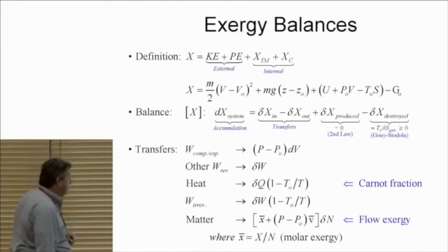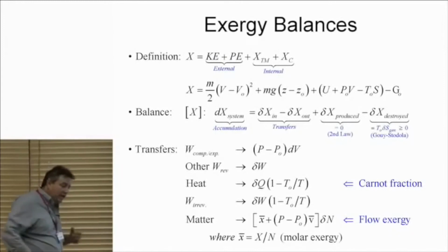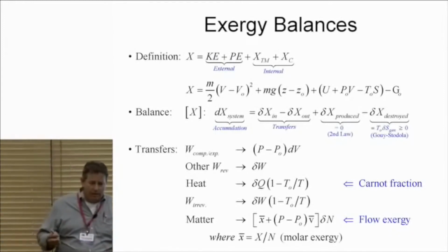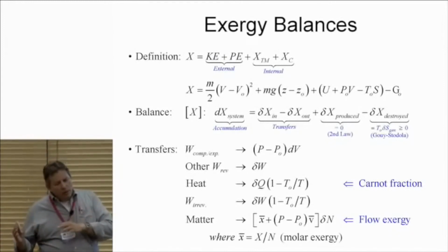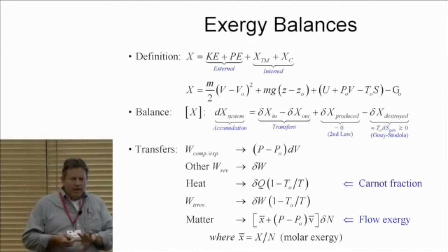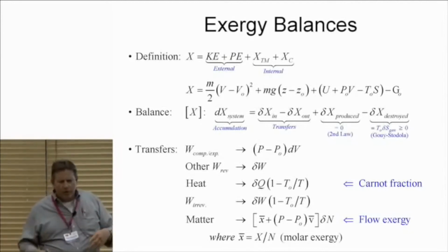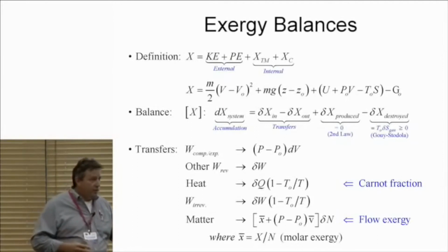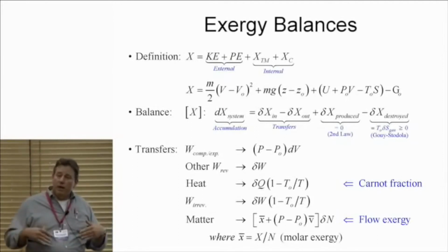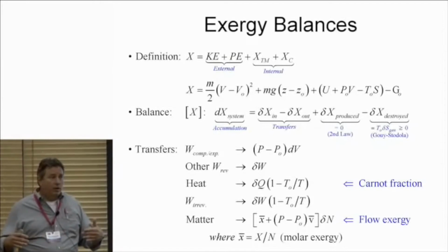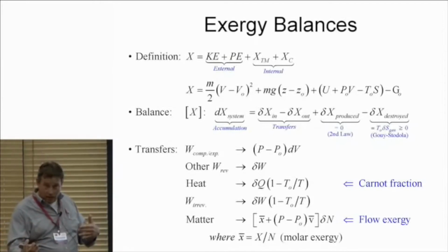Okay, balances. So exergy is just a quantity. There's nothing special about this. Most of the time when you talk about exergy, there's this question of, well, is it a property or is it not a property? It's a property of the system and its surroundings. But if you think about what happens when you actually use data for any system, you have to set reference states for that data, right?